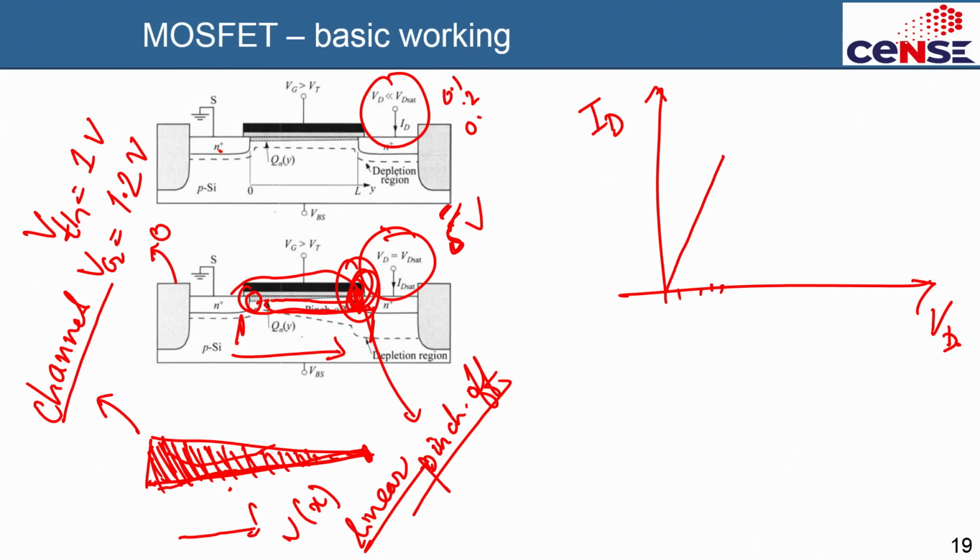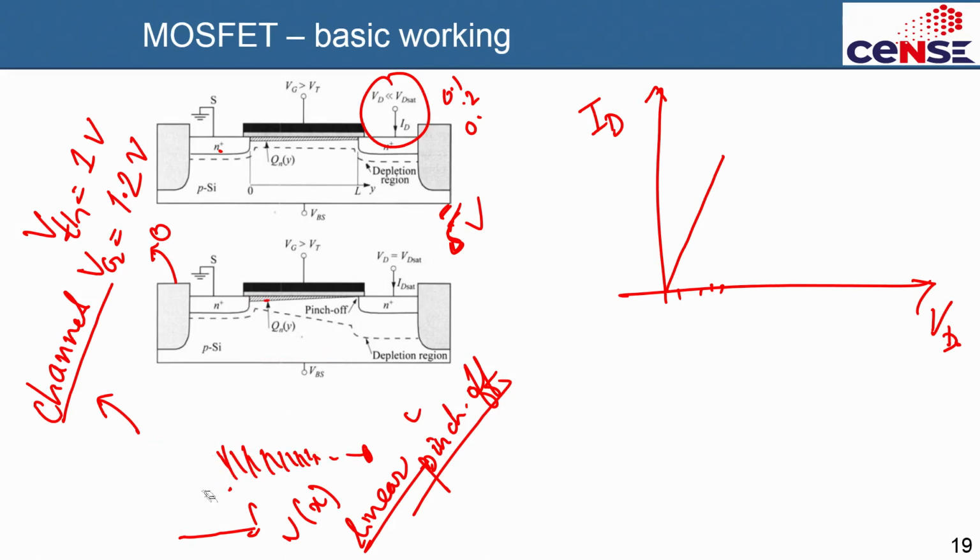At one point here, the difference of potential between this drain and the gate is essentially such that the gate is pinched off with respect to the drain, so the channel is pinched off at that point. You see that point? That's written very carefully over there. Let me rub out here again.